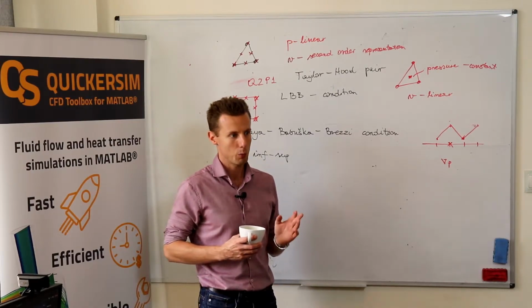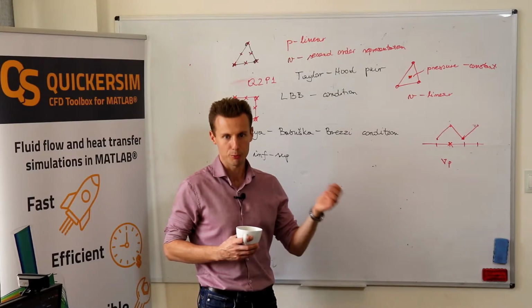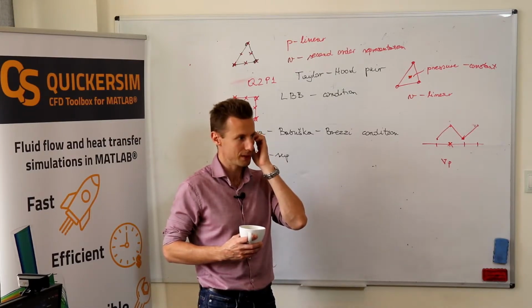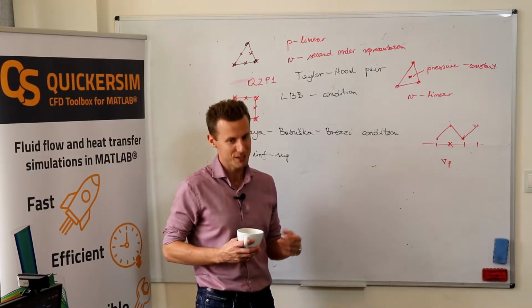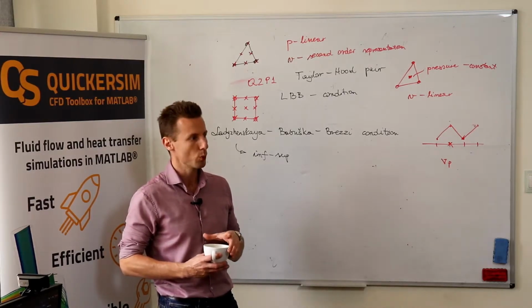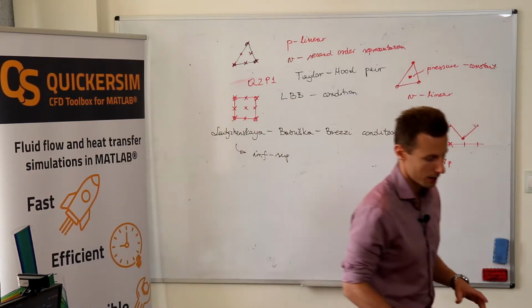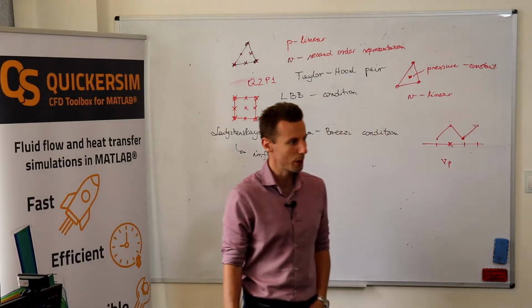If you go with the advection velocity too high with respect to the diffusivity, and too high does not mean particularly high for physical quantities, also the finite elements will produce the oscillations and wiggles.